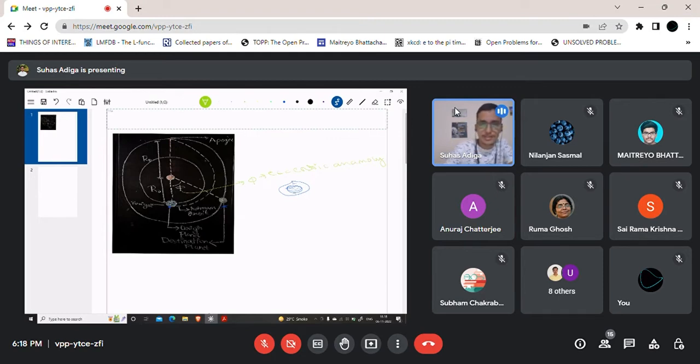So I'll say this angle is some angle phi, and when this angle is exactly phi, I give this velocity delta v1. When I give this delta v1, the spacecraft starts moving in an elliptical orbit, and this orbit will coincide with the destination orbit. And when it does, I'll give one more velocity in this direction. This is delta v2. This is delta v1, and this point I call the perigee because it is near to Earth. And when I reach this point, I'll call it the apogee.